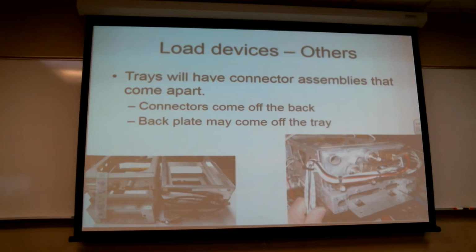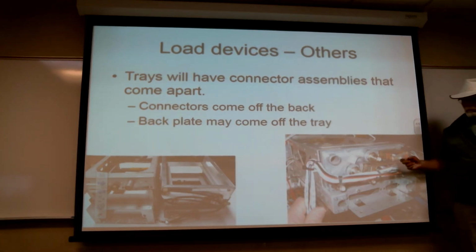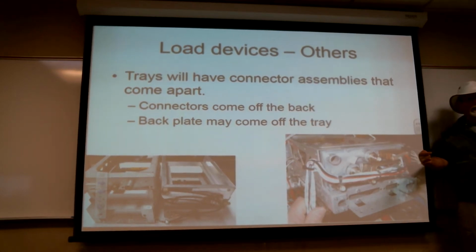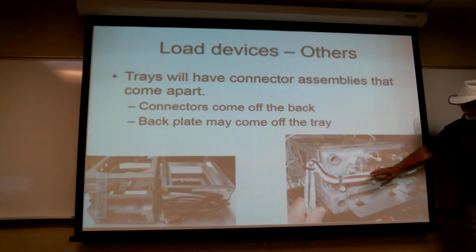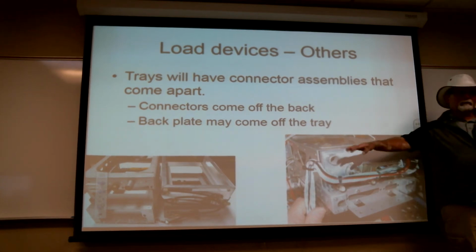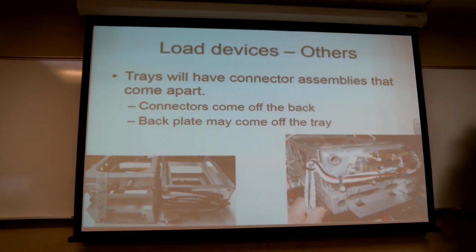Or there'll be one big lead that runs to the batteries in the back somewhere with the master relay right by the battery, up to the bus. Then it'll come off that bus straight to a circuit breaker close by, and from the circuit breaker, it'll come up to be those two wires. As well, there'll be a ground distribution bus somewhere that all the ground wires go to.